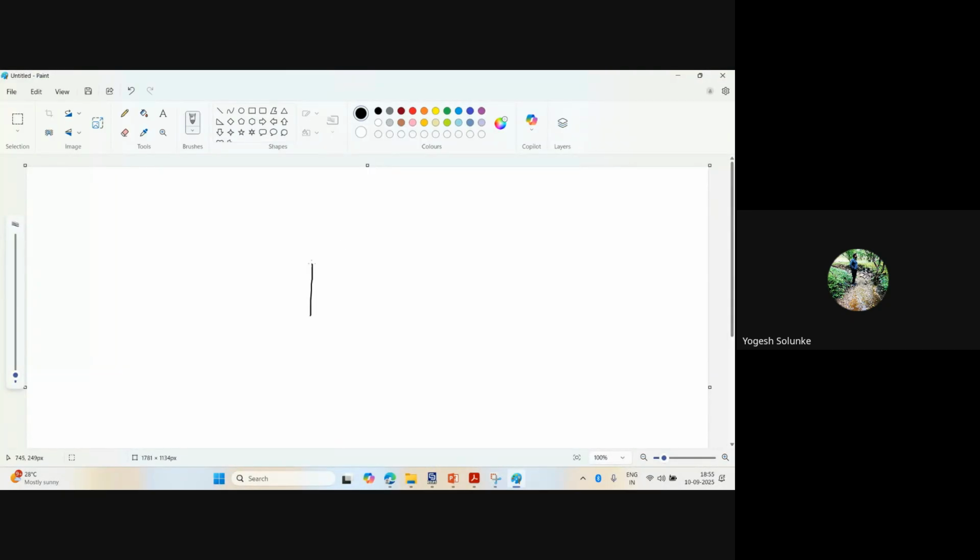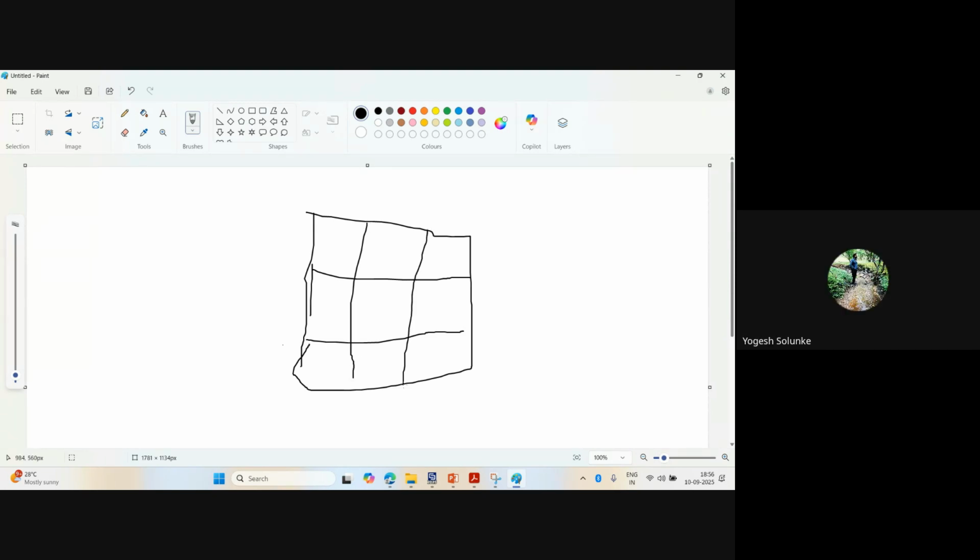When we do FSS unit cell analysis, if you have simple structures, let's say like a rectangular block, straight away we can do this analysis using this. But once you bend this, then we have to see its nearby components also. If you have a 2x2 array of these, once you have bended, you need to bring the nearby structures also into the picture. So your unit cell cannot be a rectangular one.